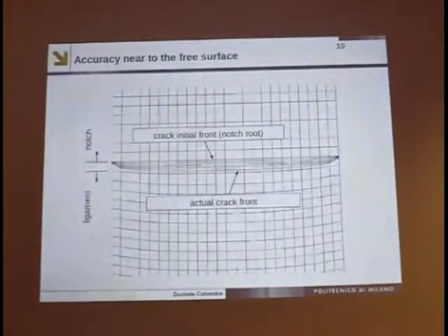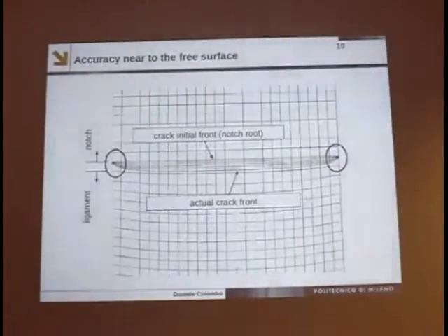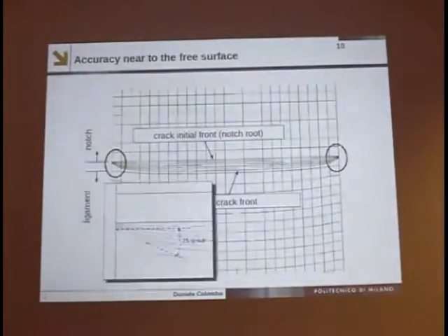This is the result. You can see that the fact that the K1 drops suddenly on the free surface generates very slow crack propagation rates on the free surface. And this is not really true, because if you check the angle between the crack front and the free surface, I obtain 25 degrees in this case. The theoretical value is about 11 degrees, because this was a titanium alloy.